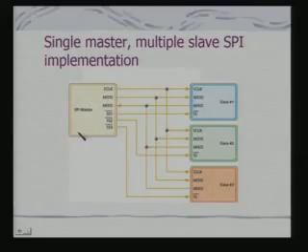So, the basic configuration in this case would be therefore something like this. Okay. So, you have got an SPI master, and the interesting issue is that in this case I have got multiple slave select lines. Just like if you remember, when we talk about interfacing memory, what happens when we interface a memory?